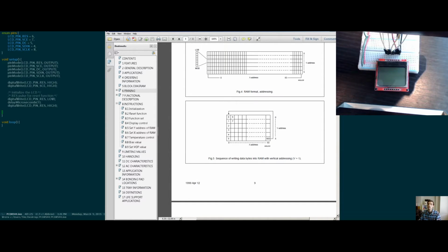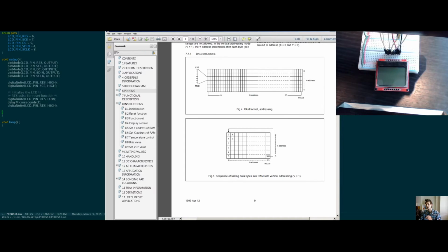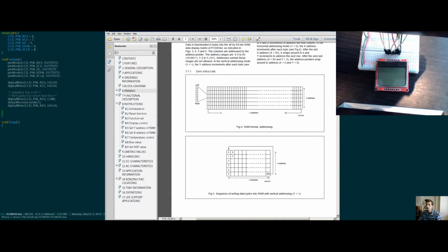So basically how this LCD works is, since it's a graphical LCD as opposed to a character LCD, because that's actually a separate kind of LCD, and those can just show characters by having those characters in internal RAM, and then you can just use your own ASCII characters in your code, and those characters will show up on the LCD if it has them in RAM, as opposed to this one where we actually need to set each pixel explicitly.